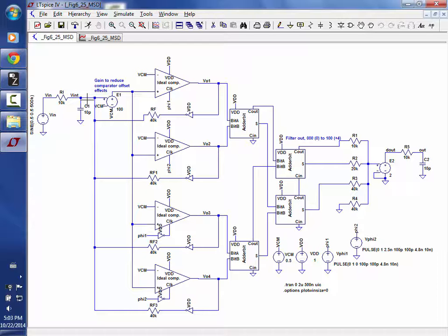You know, one is at 0, 2.5 seconds, 5 seconds, 7.5, 10. I could do it at every 10-second interval by myself, but if I have 4 people working, I can do it 4 times faster. So I'm getting an effective time interleave topology by focusing on the feedback path. Now, if I make a mistake, the mistake isn't on one path, it's shared between all of the paths. So that sharing will allow me to compensate for the mistake in the other paths.